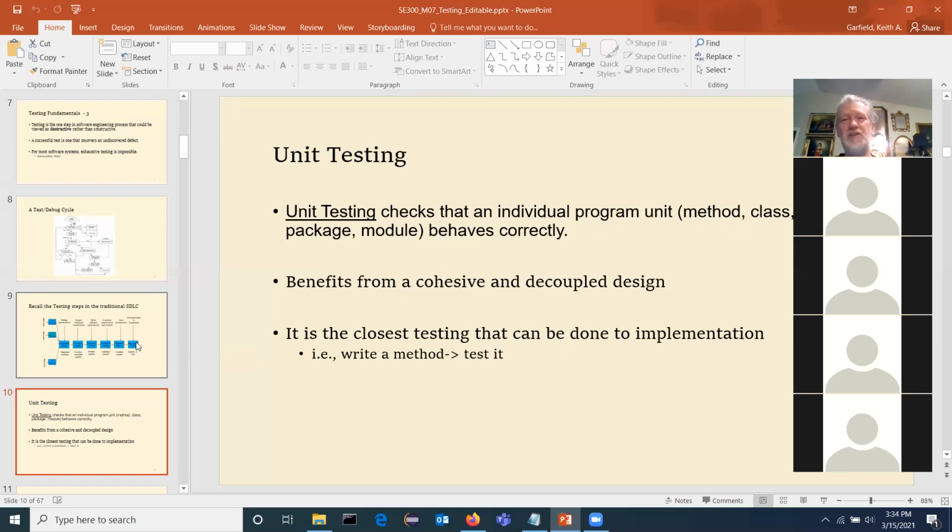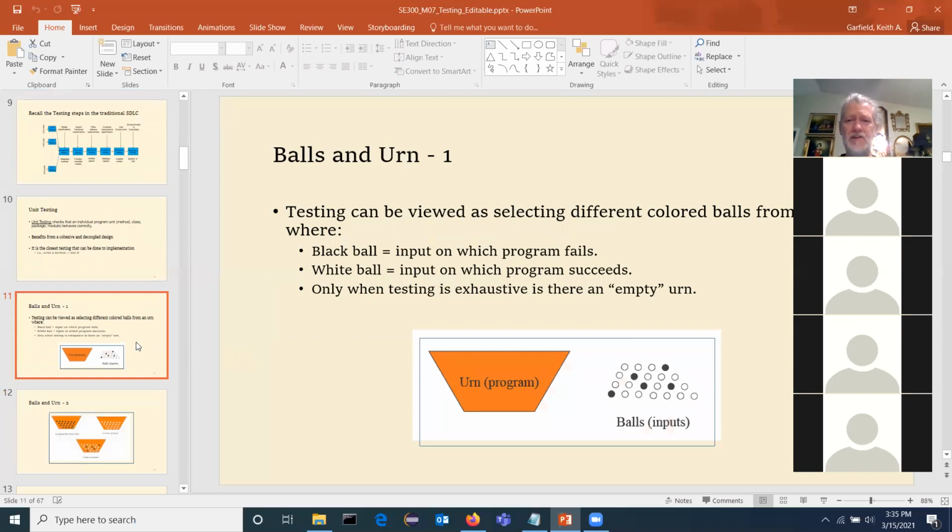So you might have an avionics box that works great on the bench, and then you put it in the aircraft and it turns out it's, I don't know, being affected by the radar unit or something like that on the nose of the airplane, or it's being affected by the nearby avionics box, and now it doesn't work anymore. So that's the difference between unit testing and systems testing. Most of our work is done at the unit testing level. Again, the good news about using these automated testing systems is when you develop your test for the unit system and then you start to do integration, you can just automatically run these tests again. That needs to be added to this course as a specific thing.